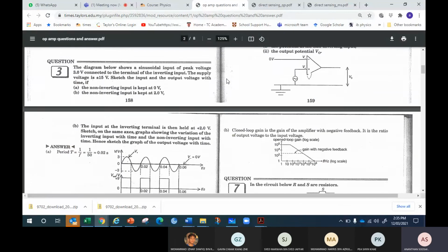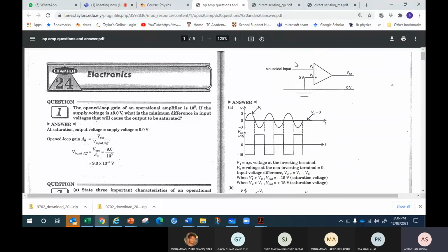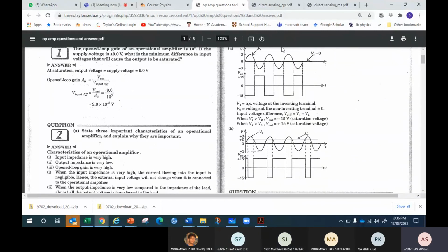Okay, I go to this circuit here. What do you think? Is it a comparator, inverting or non-inverting? Anybody? This is a comparator. No feedback. You see the input was sine, but the output is all saturated, all flat. A comparator always flattens the input, either positive or negative. That's the only thing it knows.